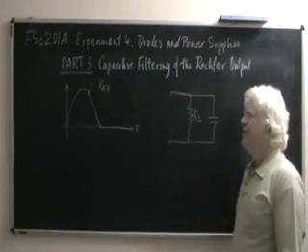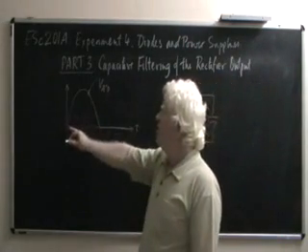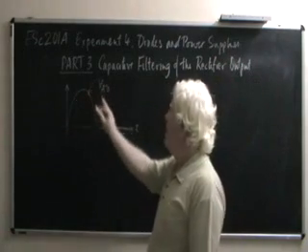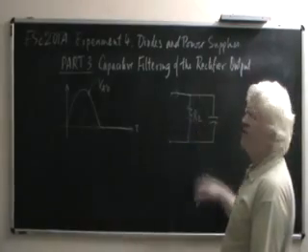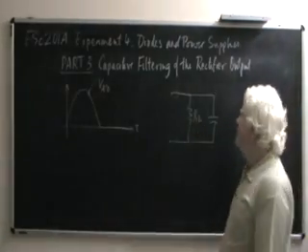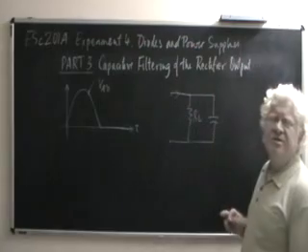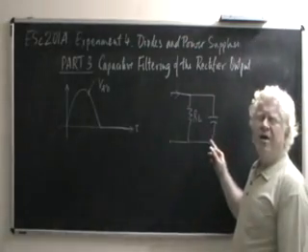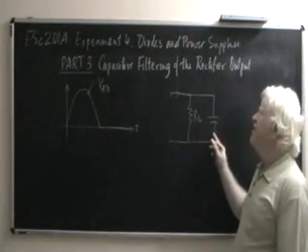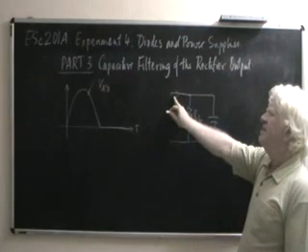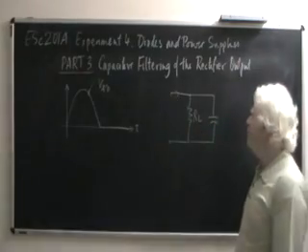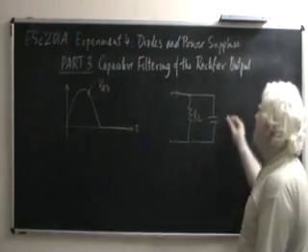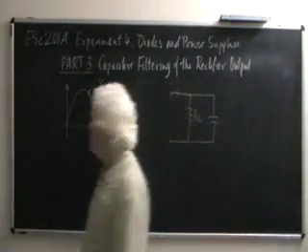When a non-zero voltage is applied by the rectifier to this part of the circuit, this capacitor will charge, provided the capacitor voltage is less than the rectifier's output. This, for example, will happen if the initial capacitor voltage was 0.